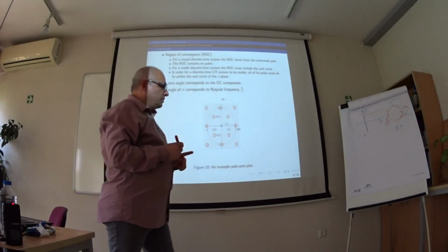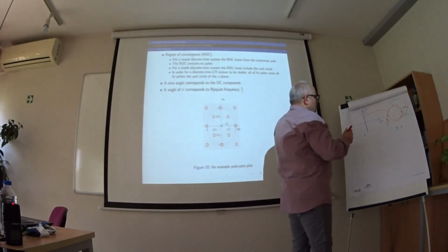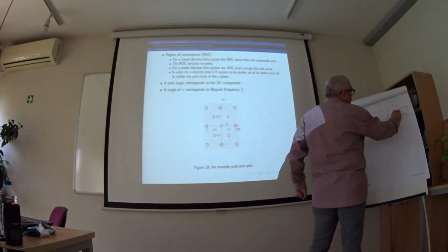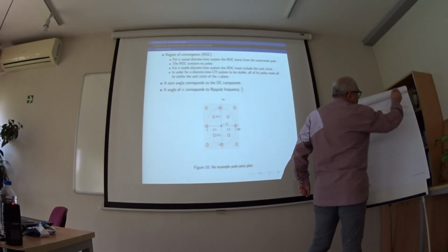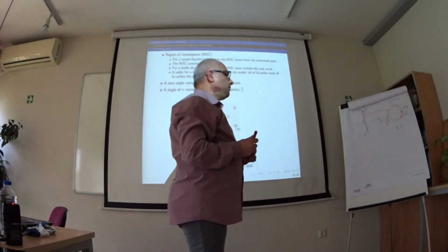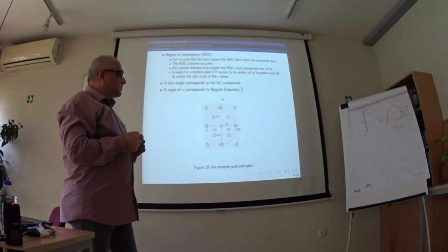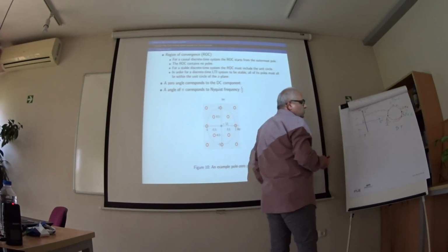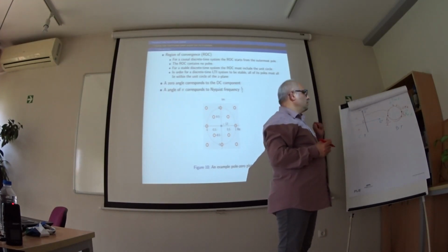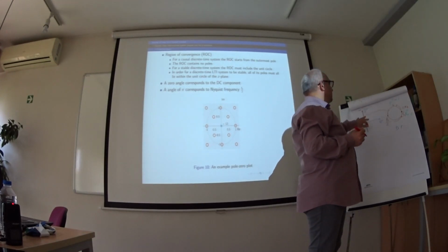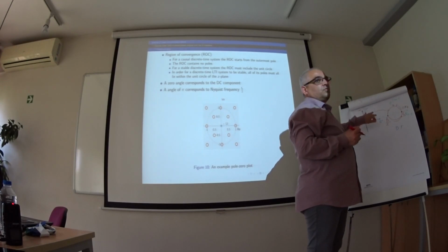In a continuous time system, we work with frequency from 0 up to infinity. For discrete time system, we work with frequency from 0 up to sampling frequency. Now, because here our stable system has poles on the left side, can you guess in digital version where the poles have to be to have a stable system?